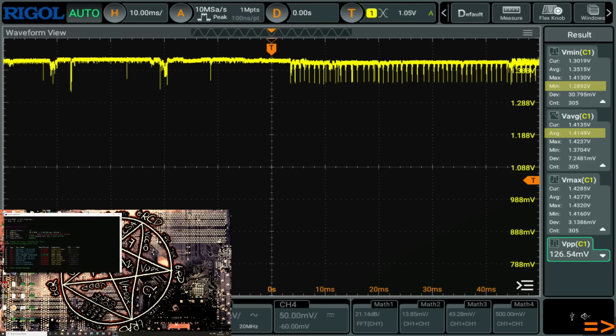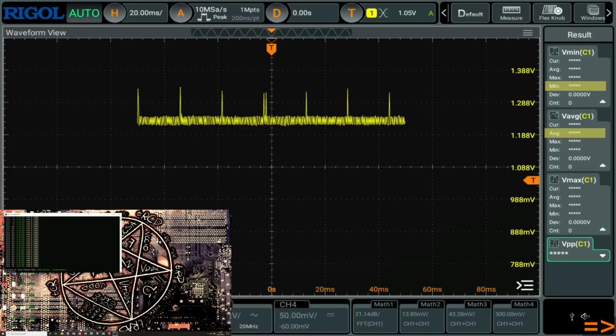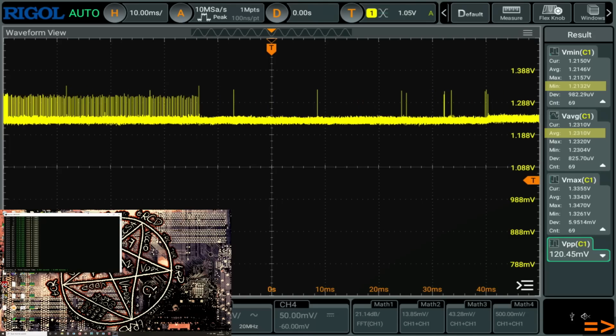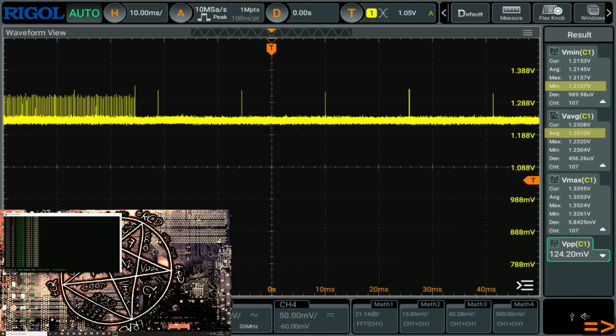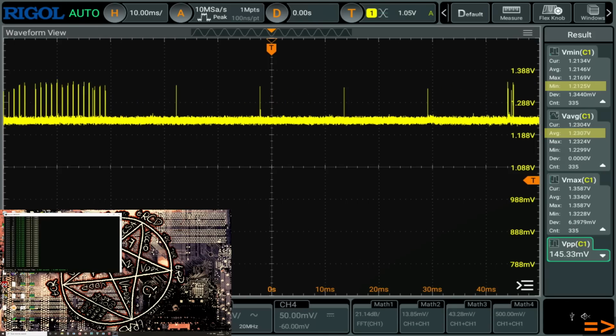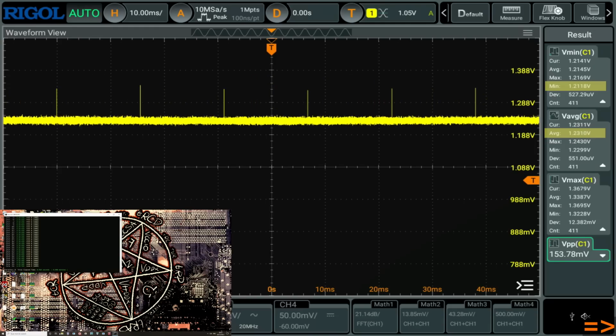But anyway, let's hit Y Cruncher. Our average voltage is about 1.23 volts. It's actually a bit high again by another 1 millivolt. Maybe I should have punched in 1.455, not that I think it would have drastically changed the results. If I don't touch the mouse, we're seeing very similar results to mode 7 without touching the mouse, about 1.215, 1.212 volts right now. If I do touch the mouse, we see like a millivolt change in the minimums. So mode 8 is very, very good.